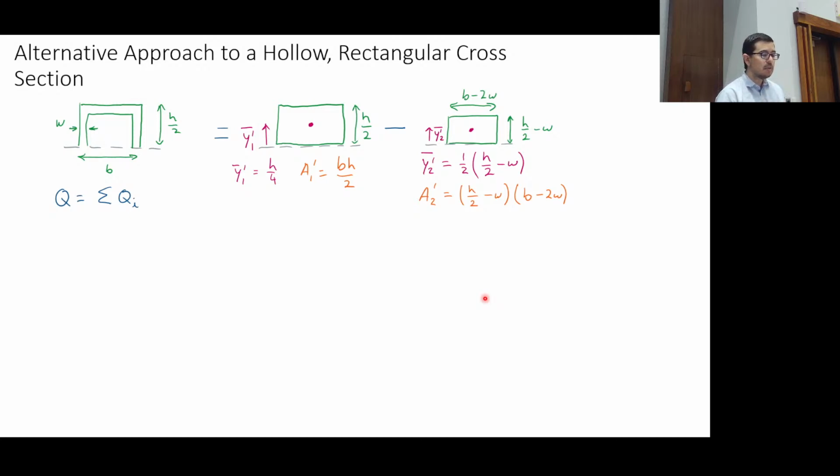Similarly, we can subtract and add Qs when we have a bottom surface that is matched, so for example, on the neutral axis. So here, if I have this cross section, I can calculate the Q of the solid piece and then minus the Q of the region that's been cut out.